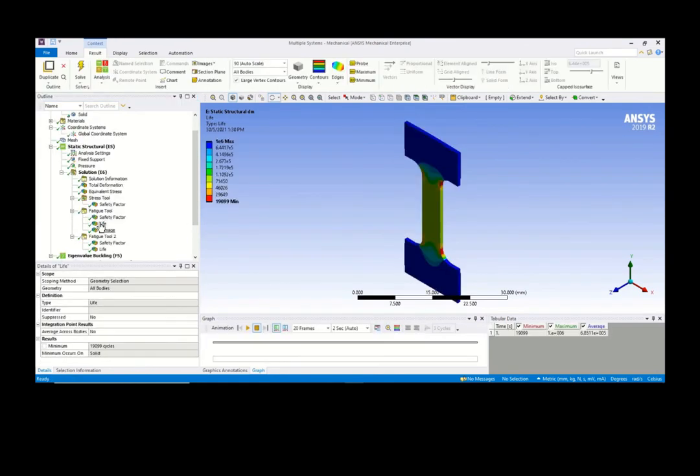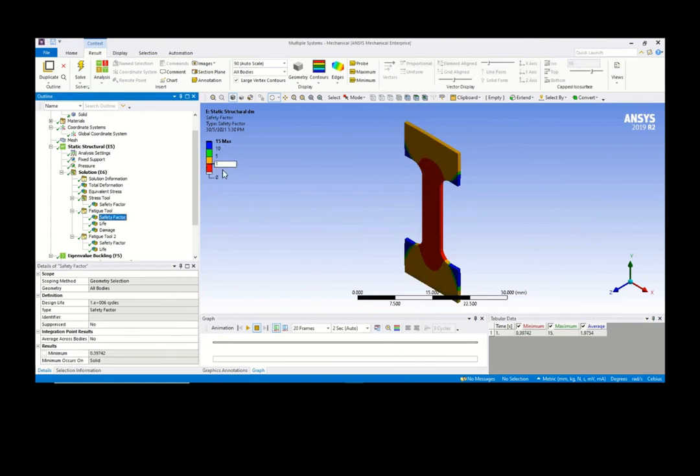Because we say that it's below, this is around 0.39. The minimum is at 0.39, your safety factor. So it's below 1, fatigue is likely to happen. Then definitely you have a finite life of cycles before static failure will happen.